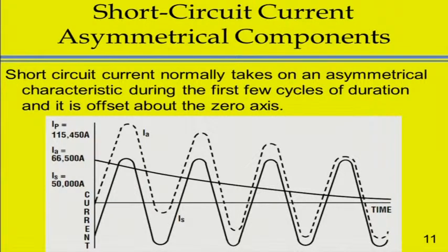in terms of coming up with how high this is going to get. So we have to look at the X over R ratio, the impedance versus the resistance, because they operate at a right angle. And so we have to look at Pythagorean theorem in terms of calculating what the resultant impedance is as we do that.